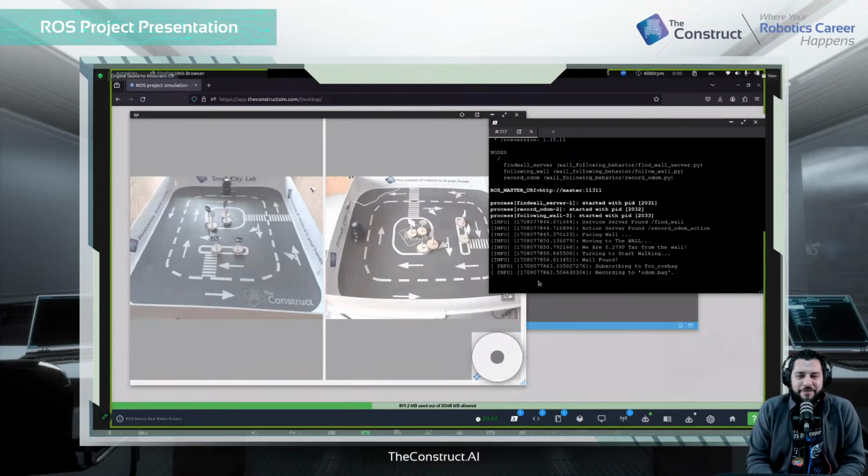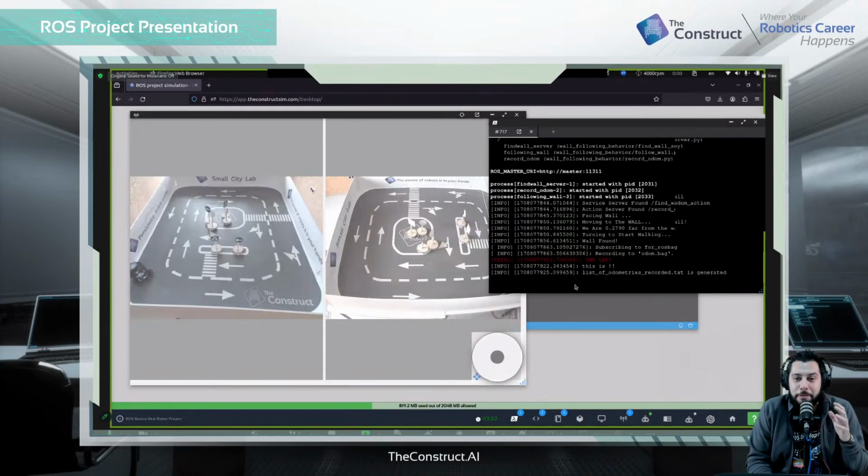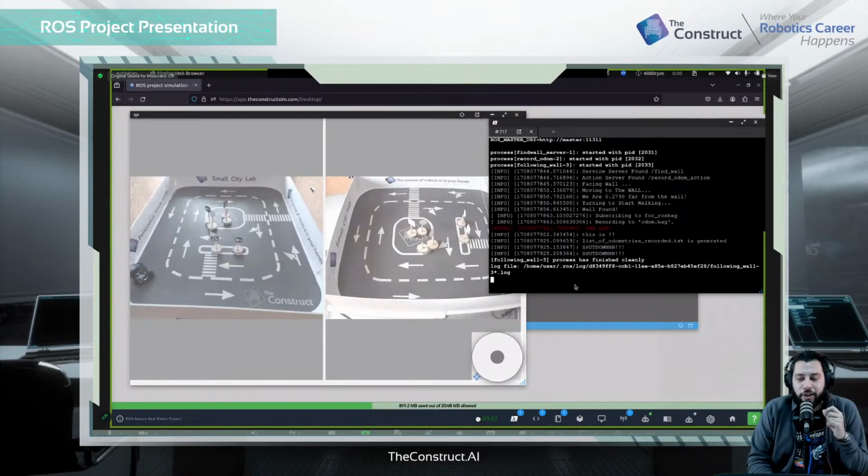Yes, I have made a PID control. Nice. I have a question about this part. I will ask you about it later on. How did it get kind of stuck or something? Is that what you mean? No, here it's just at this corner, the robot goes closer to the wall than the other corners. I don't know why. Maybe I'm guessing it's because that wall is not receiving light the way the other walls are. So maybe the LiDAR readings aren't as good. That's what I would guess. Yes, I think there's something special about that corner.